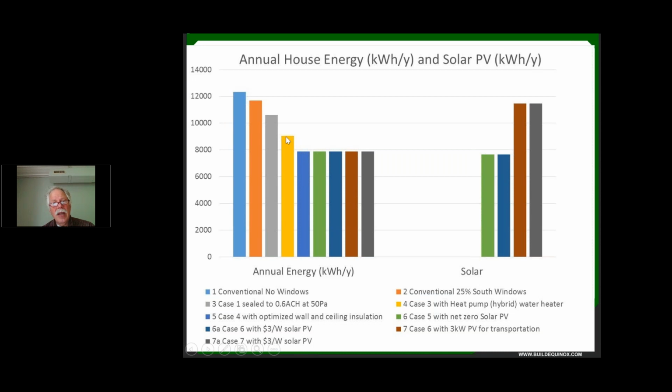And we'd also find that the ceiling insulation, which we originally had at 12 inches, would go up to about 21 inches. The reason ceiling insulation is thicker than wall is that it's less expensive. It's not because it's hotter up there. It's not because of something different in a ceiling versus a wall. Yes, there are some differences, but by and large, it's that you can blow insulation in the ceiling, and on a per cubic foot of insulation value, it's less expensive.